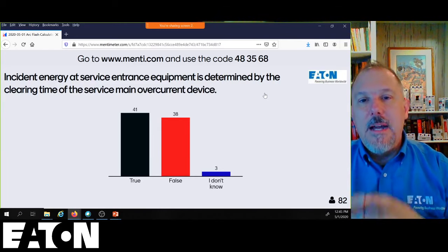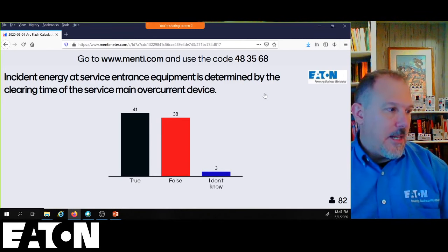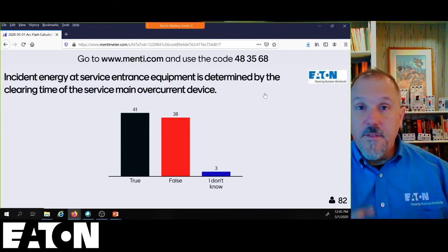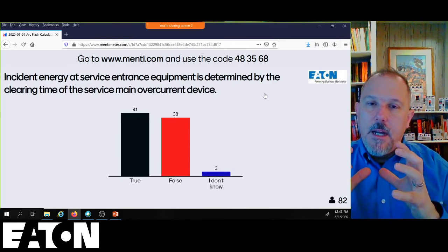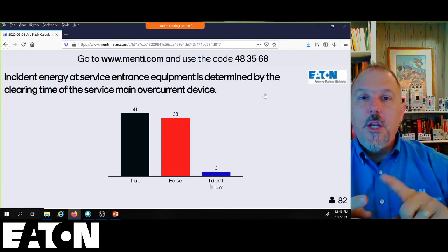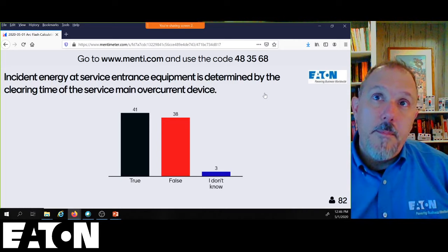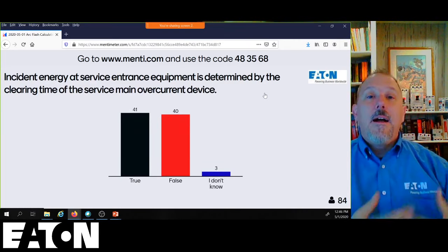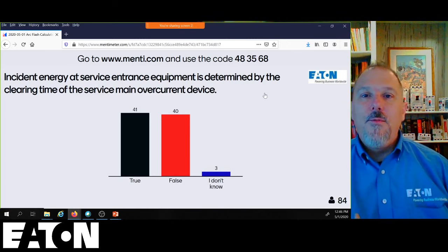And what happens in line side propagation is it takes the main overcurrent protective device that's in that equipment out of the picture. It's no longer a part of the circuit. So you can't rely on the main overcurrent device in that panel board to clear the fault. We go to the next upstream device. Now, in service entrance equipment, I see my buddy Mr. Crawshore is here. You got Tim Crawshore out there on the line side of your equipment, and what does he have?